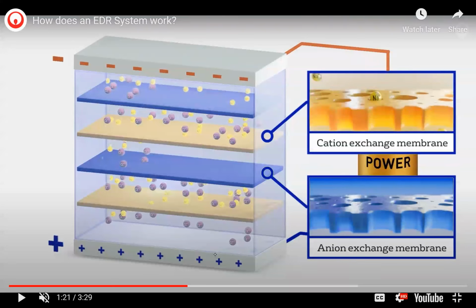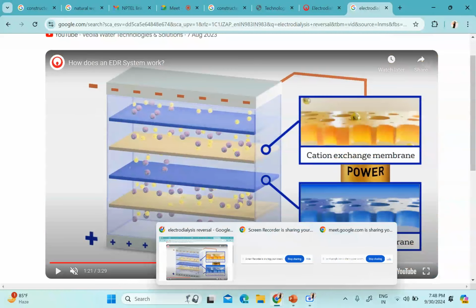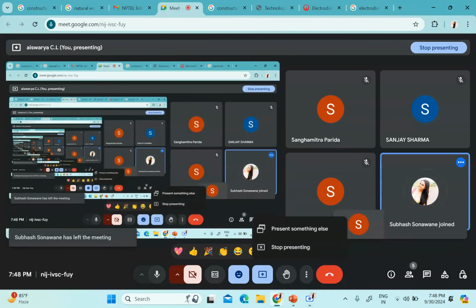In the third chamber, the brown colored surface, which is the cation exchange membrane, is passing Na plus into the second chamber. So in the second chamber, Cl minus has arrived from the first chamber, and Na plus has also arrived from the third chamber. Like that, NaCl is regenerated here and it is becoming concentrated. Got the point?